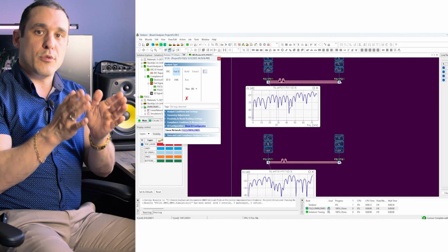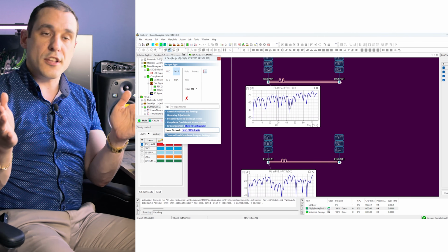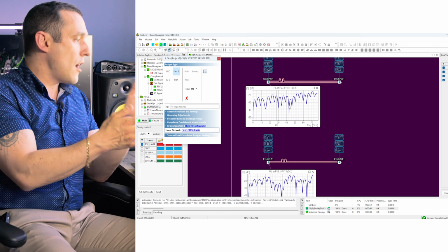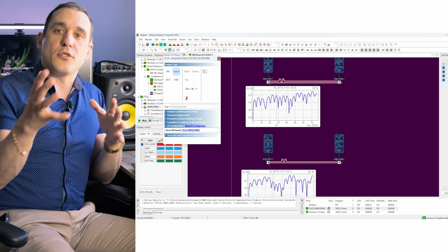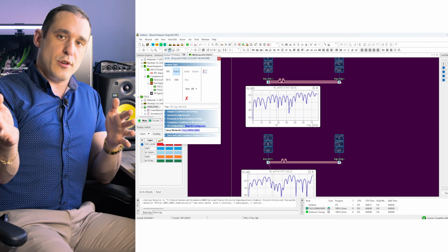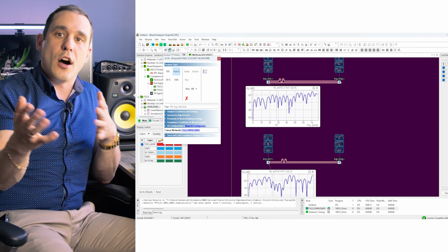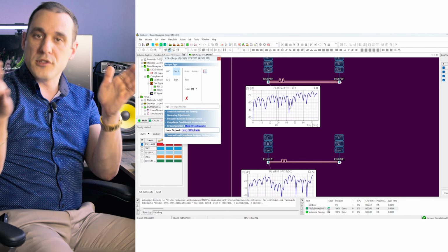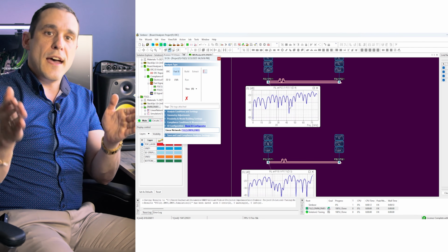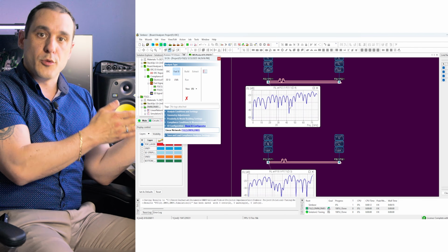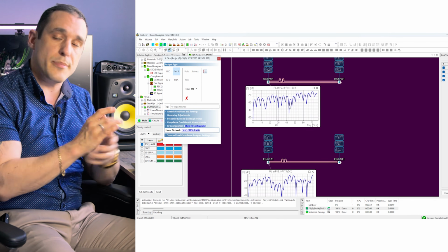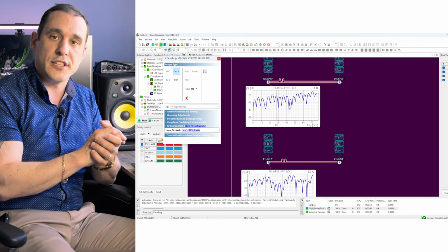If you start out with the traces spaced farther apart, you get smaller impedance deviation due to the presence of that length tuning section. And so to see why that is, go back to the previous video that I have linked in the description on odd mode impedance. If you place the traces farther apart, you use wider spacing in between them, then the odd mode impedance of each trace will be closer to the characteristic impedance of each trace, and you'll get smaller impedance deviations once you put in a length tuning section.